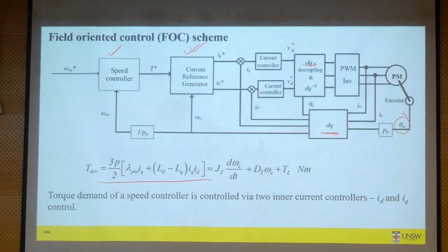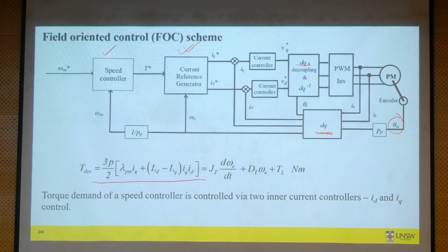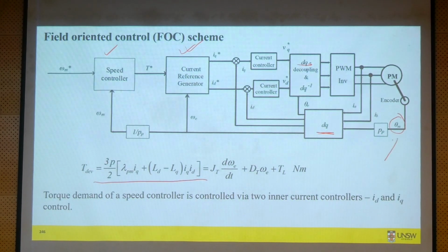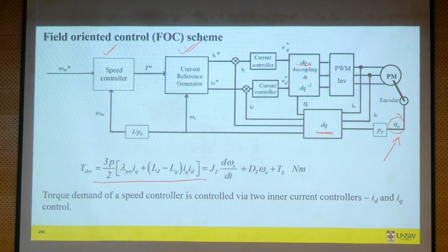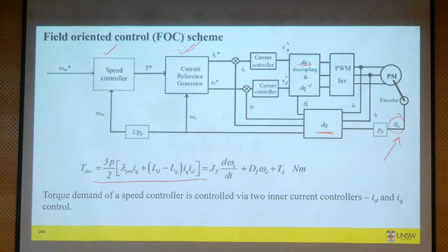If we want to do FOC sensorless, we can do it, but then you have to estimate this theta by some means. FOC sensorless is possible, but this theta you must somehow estimate.